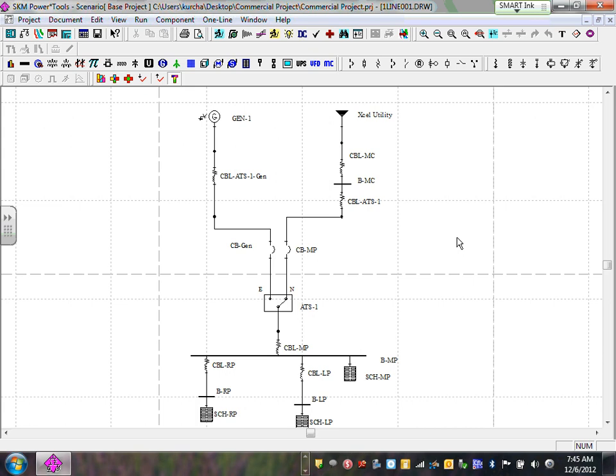We just opened the riser and we grabbed the circuit breaker and we dropped it. That's all what we did. So if you open your riser, I'll walk you quick through it. When you open your riser, stretch the neck here. And this is a low voltage switch. If you can see that way at the top, new low voltage. We dropped the 2 circuit breakers. That's all what we did. Okay.